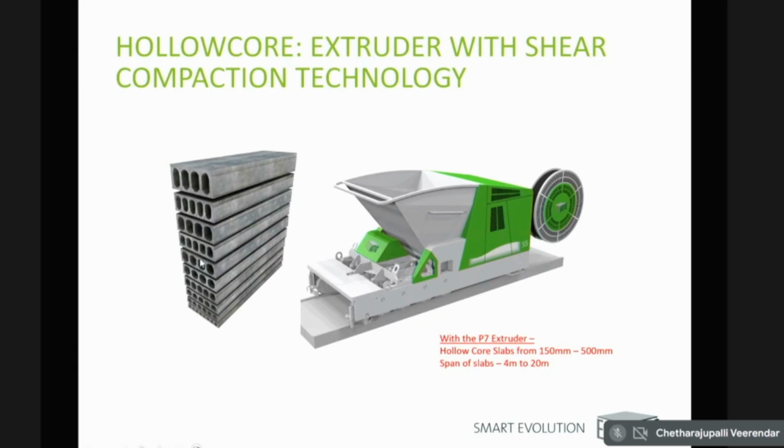The slabs are shown on the left hand side, and it is able to remove the concrete from the neutral axis, allowing only the webs where the pre-stressing strands are there to carry the load of the slab. These concrete elements are highly compacted, using M50 to M55 grade of concrete, a very dry and lean concrete with a water cement ratio of 0.3 to 0.33.